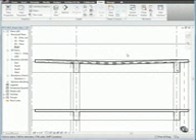Then press Escape and let's open the section view. To open the section view, double-click the section head and zoom in on the roof. You can see in the section view that the slab is sloped. The design specifies a slab that is flat along the bottom edge and that you create the slope using tapered insulation. Let's modify the slab construction to reflect this design.